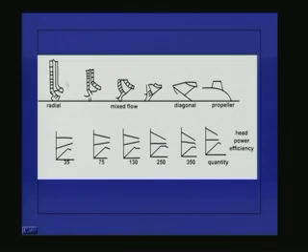Here the impeller is called a radial flow impeller. The water flows radially on the impeller. On the other end it is called a propeller. Here the flow takes place along the axis of the pump. So this is the axial flow machine and this is a radial flow machine, and typically if the specific speeds are low, one should go for radial flow machines.